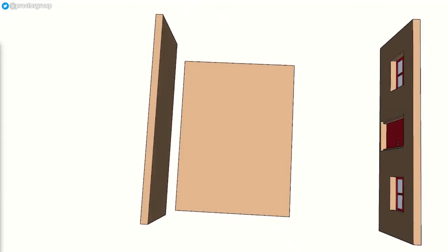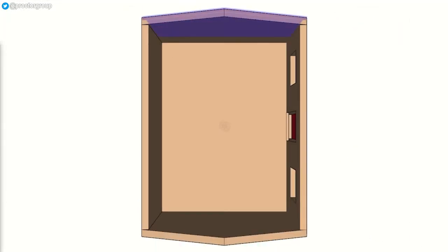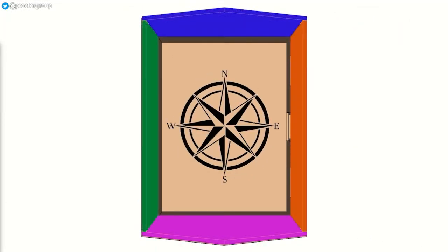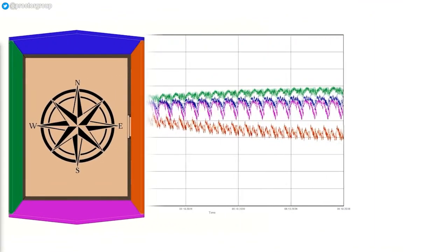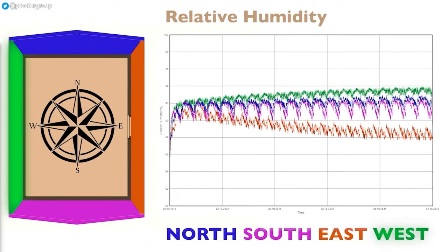The first step in this assessment is to run the model with no insulation to determine which area of the building has the higher inherent condensation risk, to establish which represents the worst case. If the upgraded structure is modelled using this element, it can be assumed the other, less onerous elements will perform adequately. We can see from the graph here that the west elevation has the highest predicted relative humidity, and therefore the highest risk of condensation occurring. So having established the worst case scenario, we can now move on to a more detailed assessment of the wall